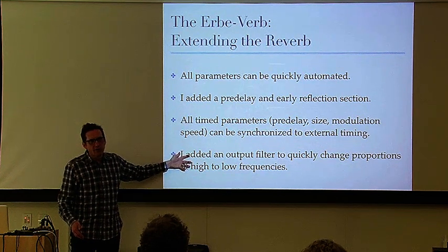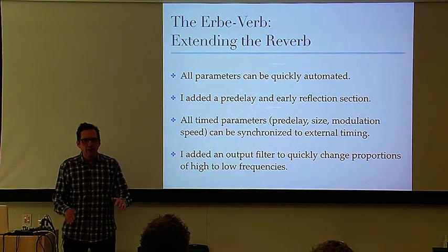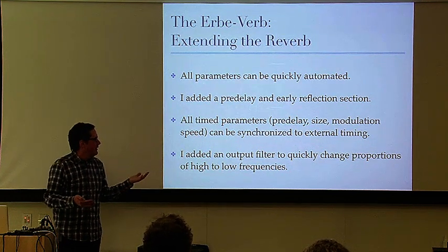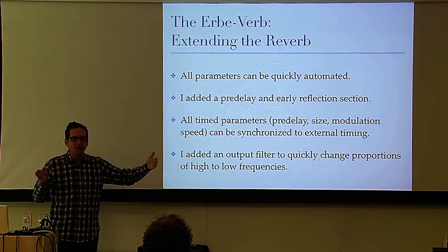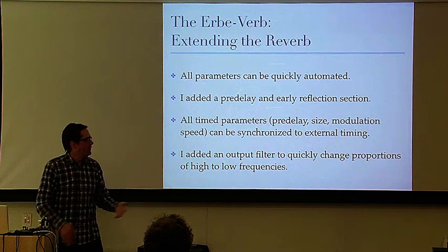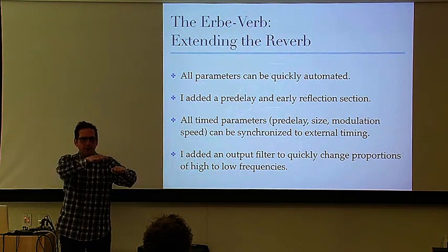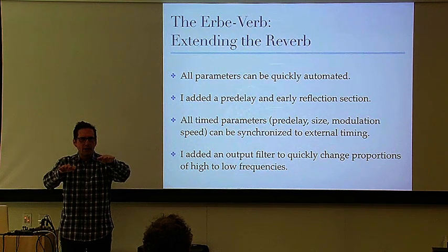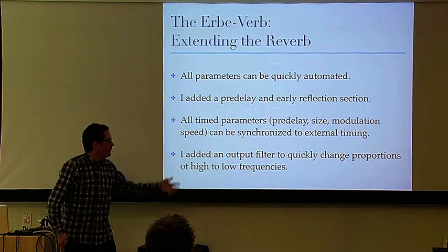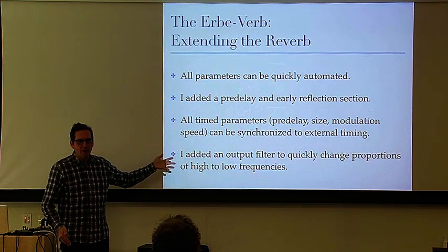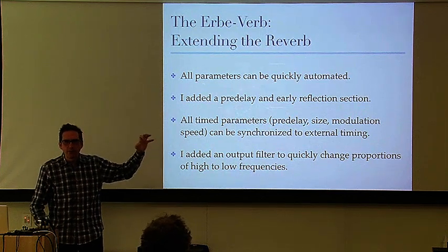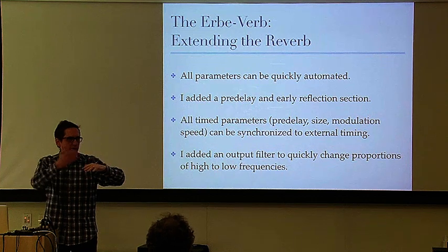An output filter on a reverb actually makes a huge difference. And if you can quickly, with one knob, make things darker or brighter, this is great. If you add a 7-band parametric EQ on the output of your reverb, it's nice, but no one wants to turn all those knobs, especially not in the modular realm. So what I had to do was tune a 3-band filter, low, mid, high, find crossover points that worked, and have one knob that does that or that, to make it quickly brighter or darker. Once I added that, lots of complaints about the reverb went away. People love suddenly making this a really bass Jurassic Park sort of reverb, or to just focus on really bright stuff and take away all that darkness that might obscure instrumental stuff on top of it.